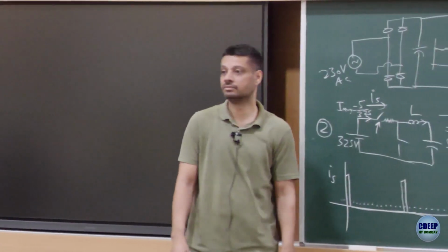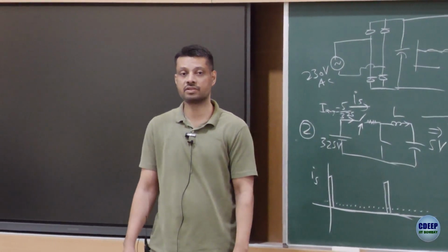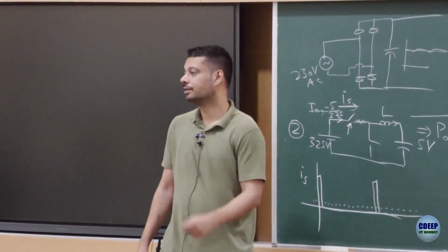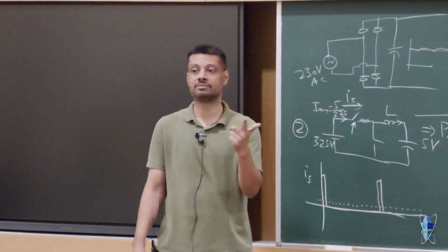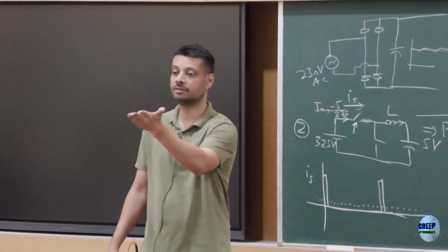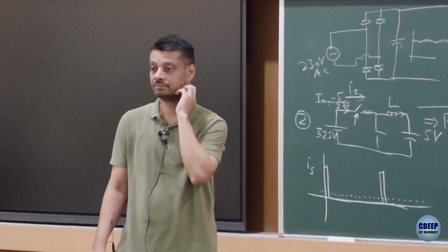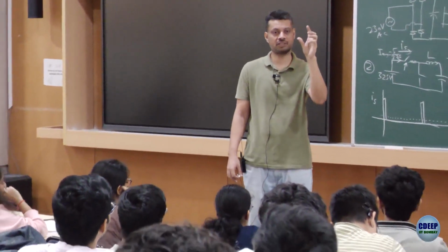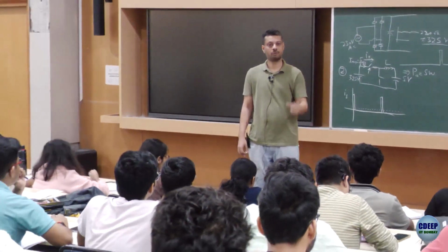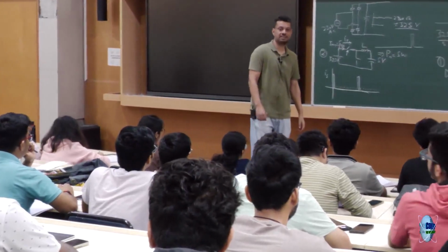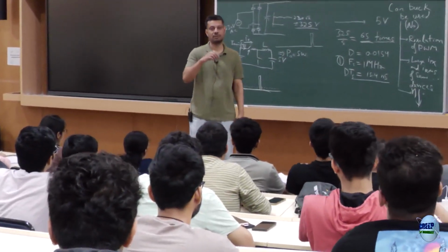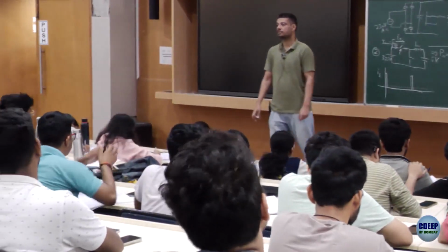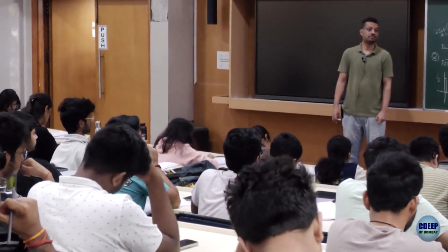Any question? No questions? Okay. What is a linear regulator? It's kind of a voltage divider using a MOS instead of a resistance. So that MOS will operate in the saturation region. It will act as a current source multiplied by the load resistance and give you the voltage, right? Any question? Okay.